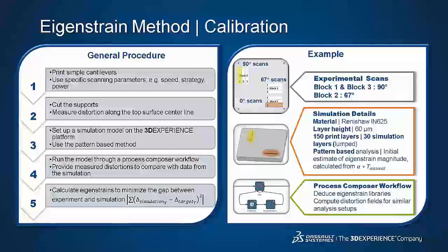Set up a corresponding simulation model in the 3DEXPERIENCE platform using the pattern-based Eigenstrain method, and run the simulation through a process composer workflow. Provide the physical measured data, and calibrate the Eigenstrain tensor components to minimize the gap between the distortion from experimental measurement and the numerical simulation.